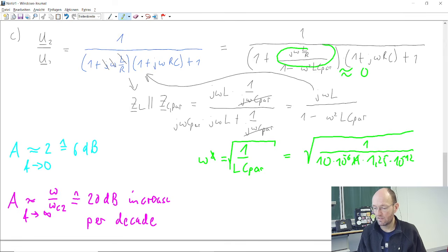Okay, and Henry is volt seconds per ampere. Farad is ampere second per volt. So the amperes will cancel each other, the volts will cancel each other. We just get seconds square left, and the square root of second square will be second, so 1 over second, which makes sense.